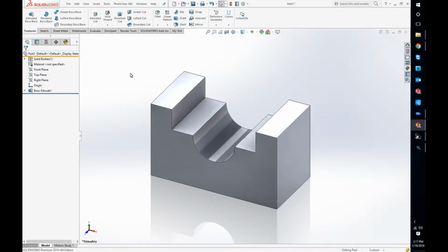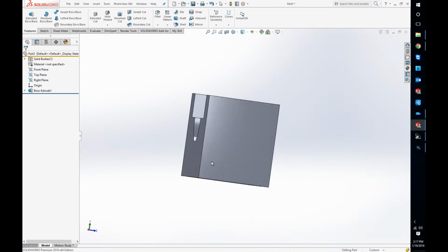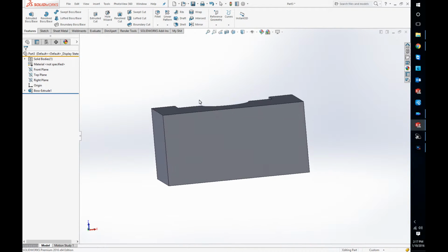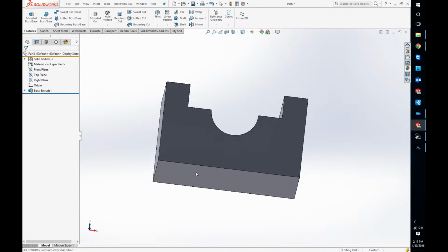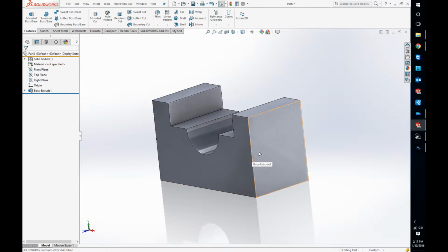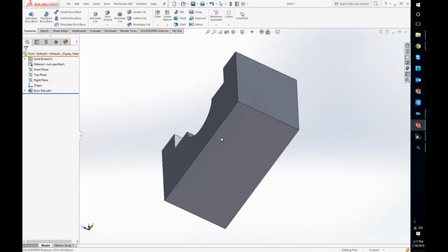Okay, so as you can see here on this quick build, we're looking at a fairly simple block. The main concern when working with a block of this type is picking the right approach to what angle and what direction you want to go about building it. To do it in its simplest manner, you would want to pick a profile view such as this position here and sketch this face. That would allow you to sketch the entire block in one single sketch and then one extrusion for your depth, to give you the shortest number of steps.